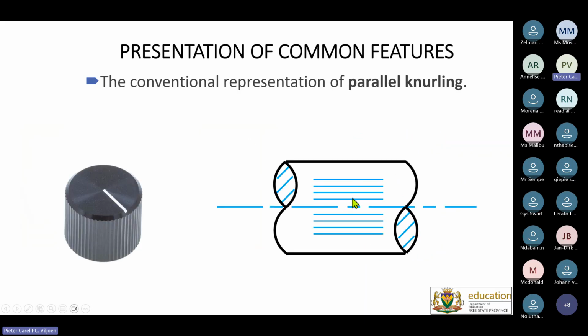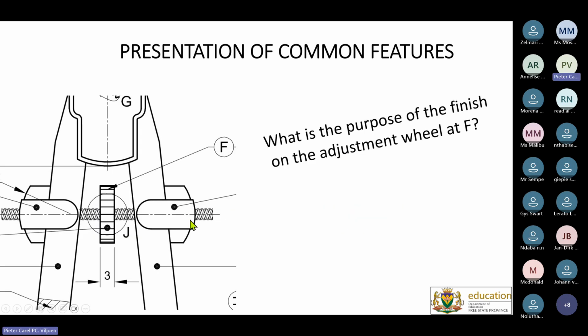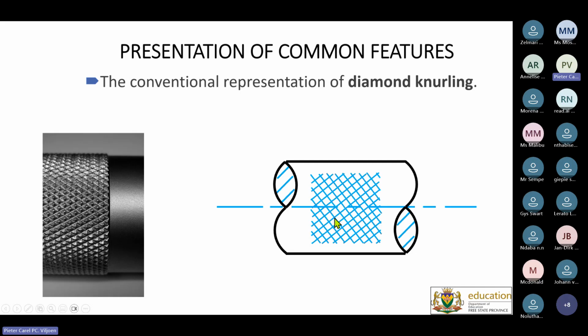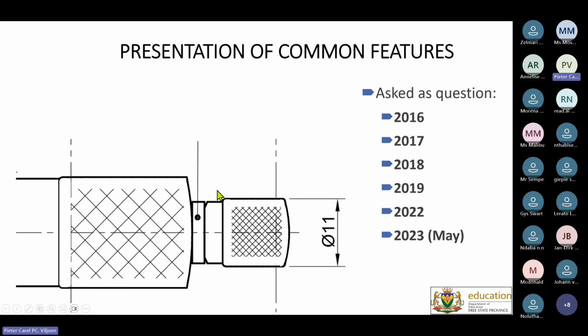Okay, and then parallel knurling. I think it's something familiar with them, so you can explain that. Normally, your radio knobs, your jump bars, and those types of things all have knurling. This is parallel knurling, and this is also diamond knurling that you can get. What is important about knurling is the fact that there must be a side open towards the inside of this part over here to show the detail is inside and not from top to bottom, left to right.